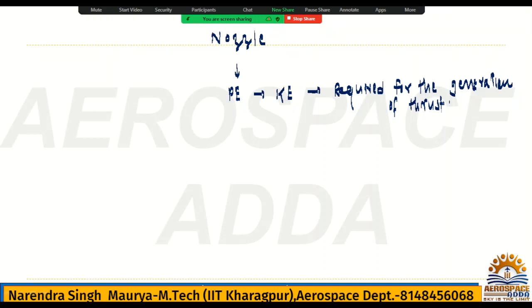So how is this conversion, I mean potential energy to kinetic energy, possible? It is possible by the geometrical shape of the nozzle. Okay, by the geometrical shape of the nozzle. So based on this geometry, we have two types of nozzle: one is the convergent nozzle, and one is the convergent and divergent nozzle. Okay, so the function of nozzle you have seen here.